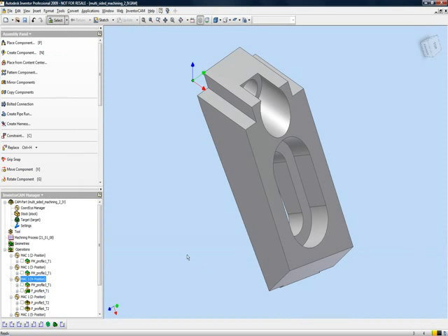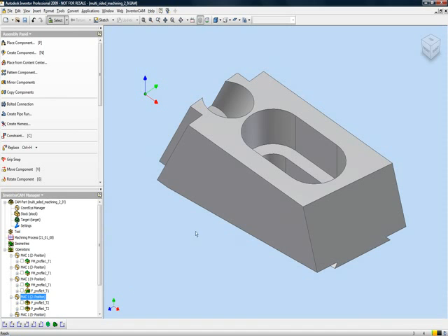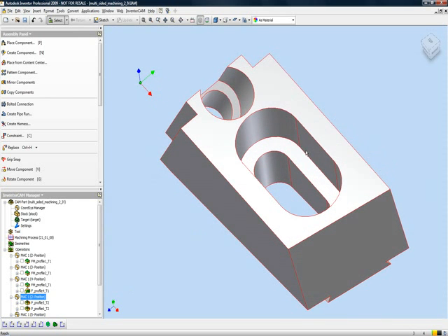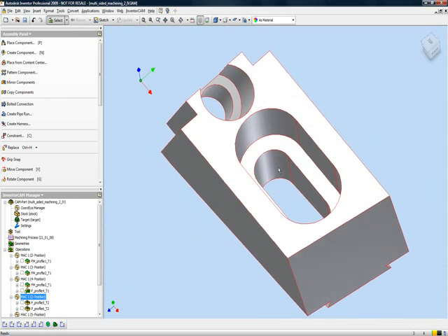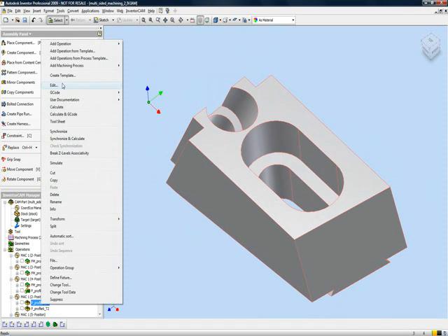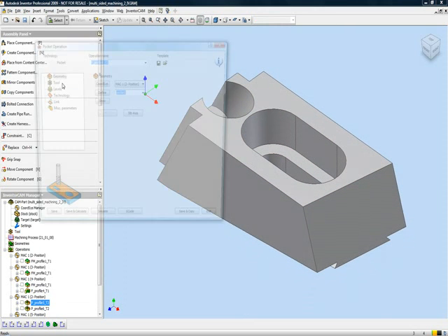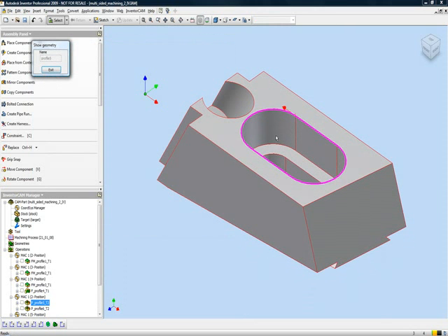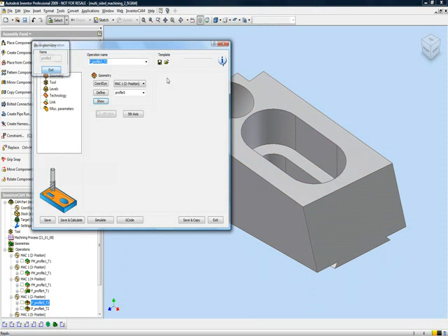Now in my next operation, I've decided to work back on Mac 1 position 2, and I want to mill out this pocket as shown over here, plus this inside pocket as well, those two slots, and I'll be using a pocket operation. In my first one, if I go into the operation itself, you'll see that my geometry is the bigger slot that's on top.